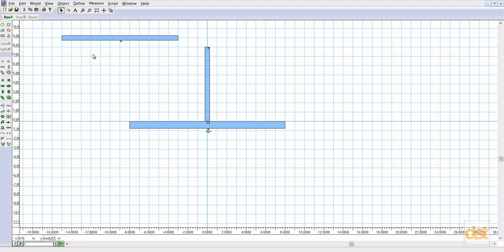Click on the arrow tool to exit that mode, and then we can simply click, hold the mouse, and drag a pick box. So I'm highlighting these two points. The other way to do it is to hold down the shift key and select the points individually. Notice with those two points selected, the join tool has become active here. So if I click on join, it joins those two bodies together. If I click, hold my mouse, and drag these parts, I can see that they're constrained properly where I wanted them to be constrained.